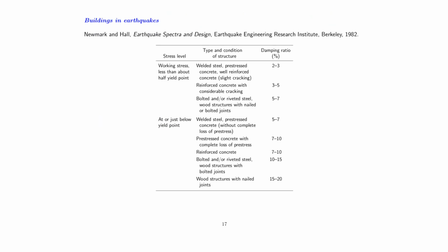The damping ratio also depends very much on the type of excitation you put to your structure, because as we've seen, the equivalent damping ratio depends on amplitude if you have a nonlinear damping model. So in case of earthquakes, you will have a very large, strong, violent excitation of your structure, and that means you will actually have larger deformations that could result in larger apparent or equivalent viscous damping parameters.